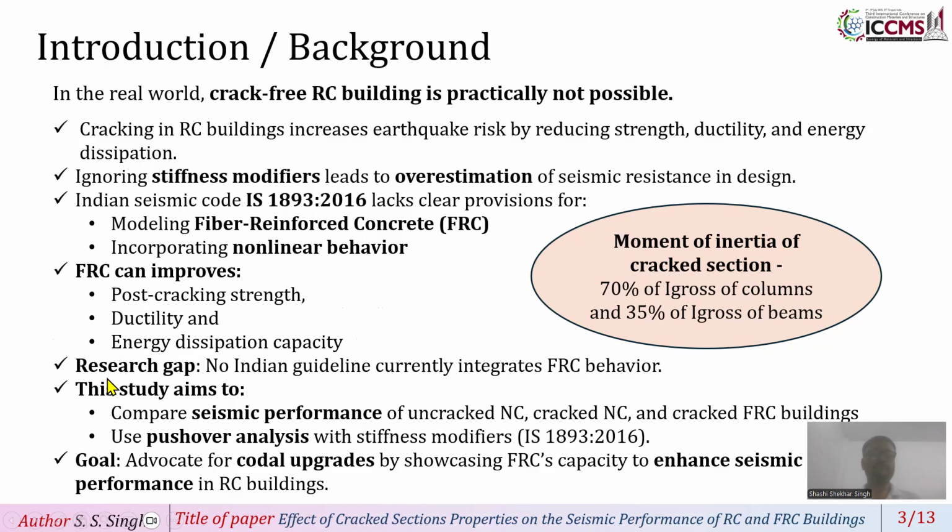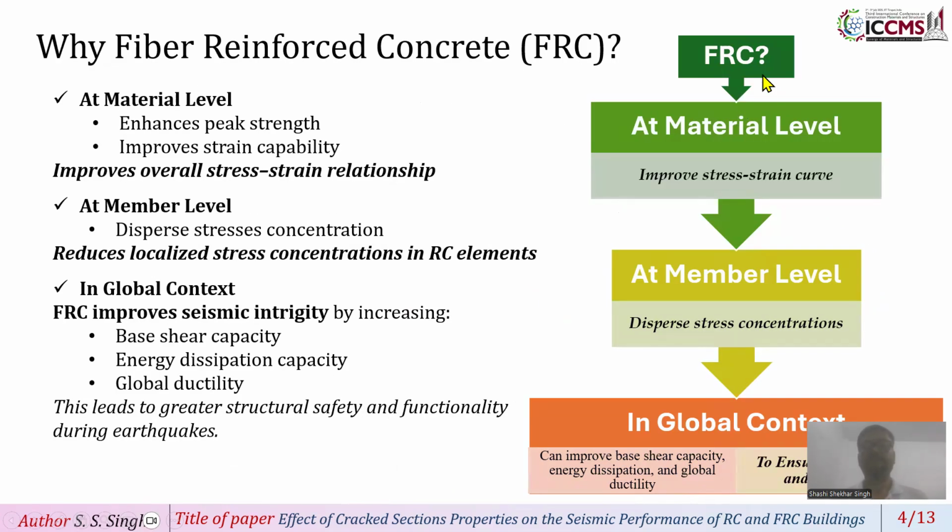From the above, we find the research gap. No Indian guideline currently integrates FRC behavior. This study aims to compare the seismic performance of an uncracked normal concrete building, a cracked normal concrete building, and a cracked FRC building. The second aim is to use pushover analysis with stiffness modifiers from the Indian code. The final goal is to advocate for a code upgrade by showcasing FRC's capacity to enhance seismic performance in reinforced concrete buildings.